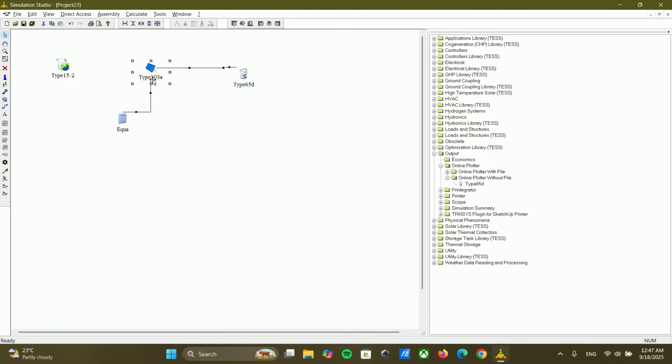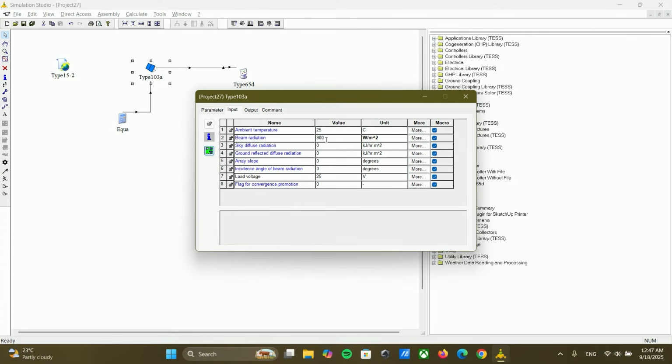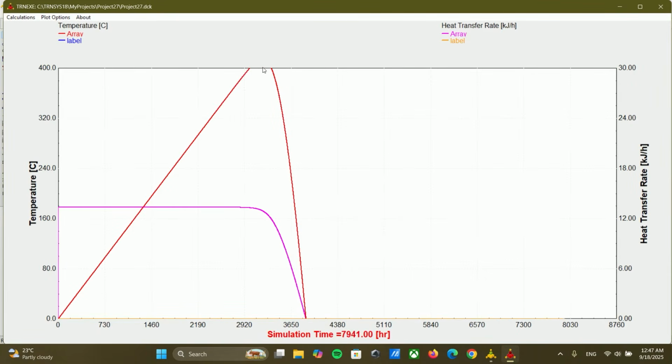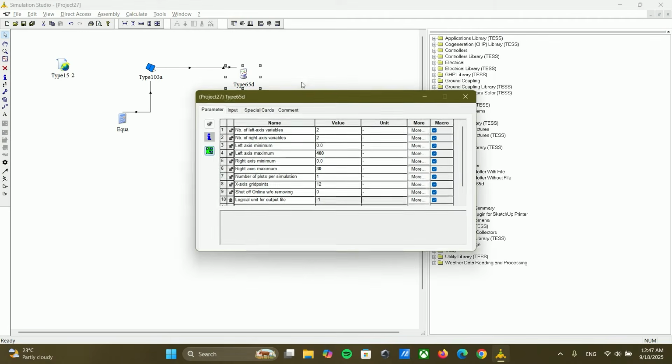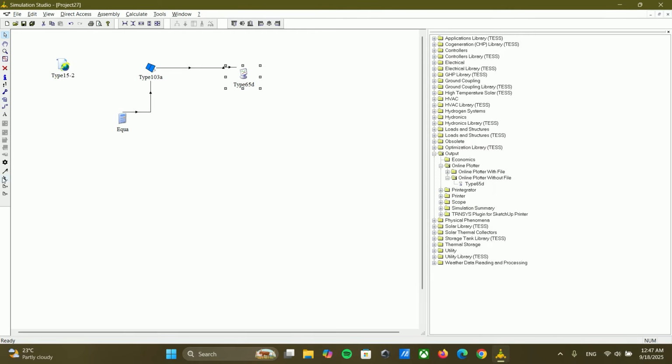modular array of panels. And if I change this to other values from 900, you would see the change as well. So I've also included, you can see it's way up there, so it's above 400 watts. And this is not temperature, so you could change this as well. I could change it to, let's say, power for the left axis, which is watts, and the right axis would change to current, which is in amperes. So as you can see, we've seen this delicate change.